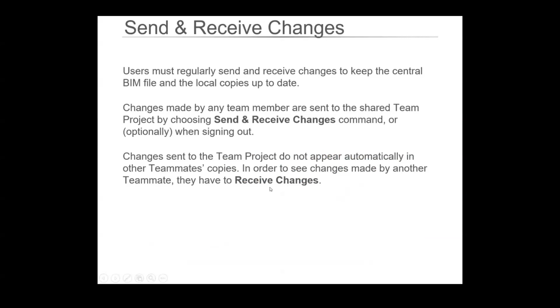And sending and receiving, it's always important to regularly send and receive, especially send. ArchiCAD has this habit of, as you do more and more work, building up a sort of internal memory, and this works even on a standalone PLN file. You notice sometimes that it starts doing funny things, or it gets slow, or it clogs up, crashes. Usually it's a result of the memory getting overloaded and it just can't take anymore, so it crashes out. So if you're working on a standalone file, Control S pretty frequently to save. ArchiCAD does save regularly in the background as well, but doing your own save clears all the memory out and gives you a fresh start.